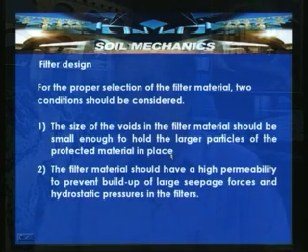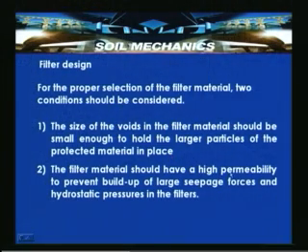Criterion number 2 is that the filter material should have a high permeability to prevent the buildup of large seepage forces and hydrostatic pressures in the filter. So, it should be freely drainable. If these hydrostatic pressures build up, then again there is a problem of endangering the structure.